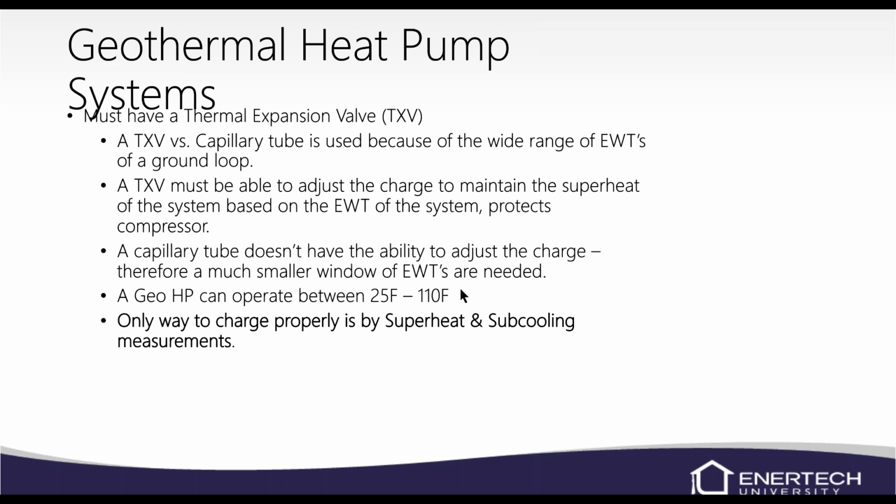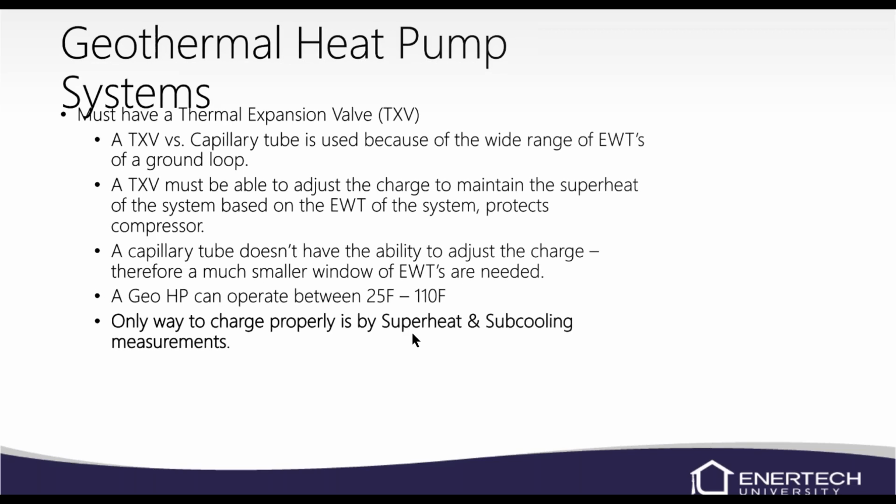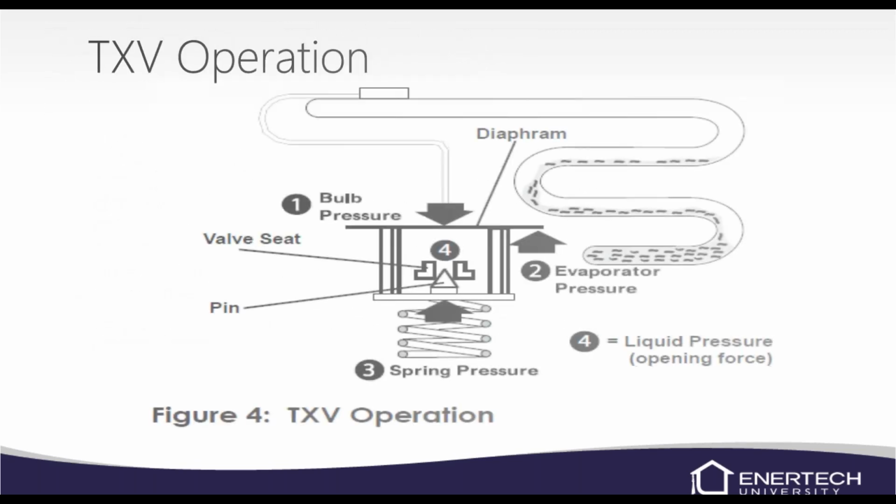The only way to properly charge an Enertech geothermal system is by superheat and subcooling. Now, that being said, we do have refrigerant charge amounts listed on the unit itself. So you can always weigh the charge in if you know that there's none in the system. But if you're checking a refrigerant charge, then you'll check it with superheat and subcooling. And we'll get to that here in just a few minutes.